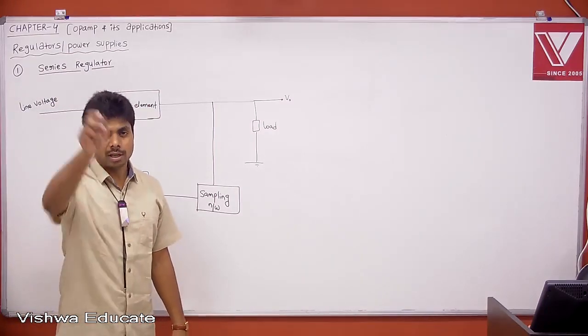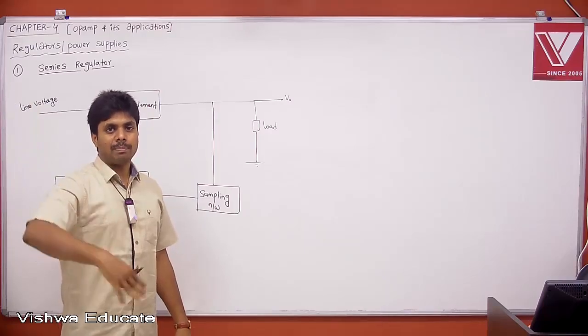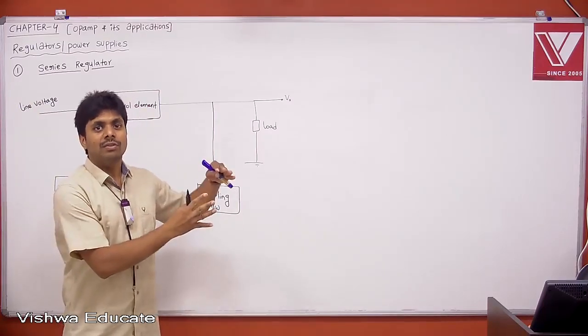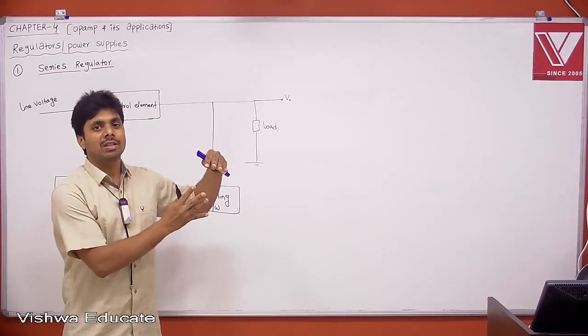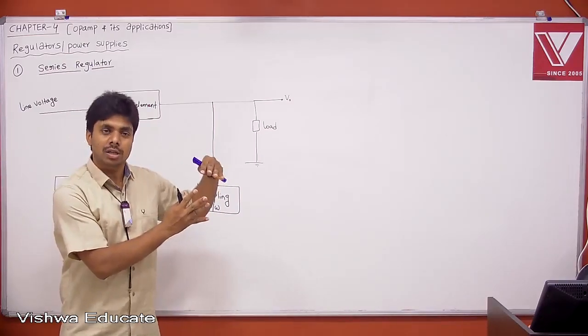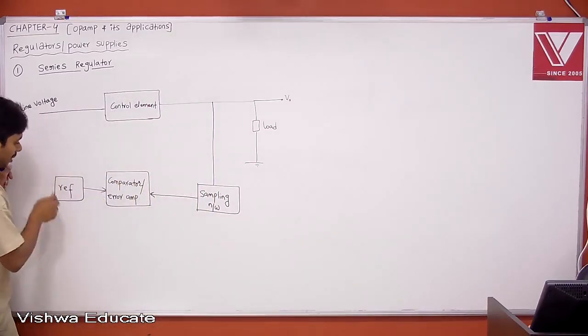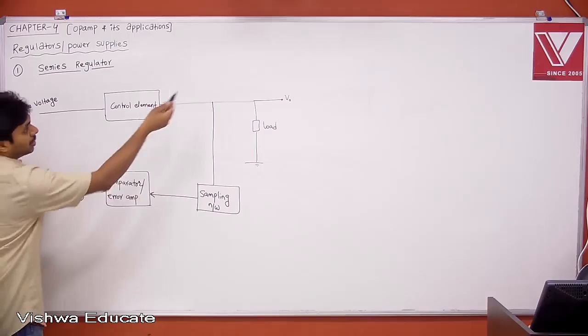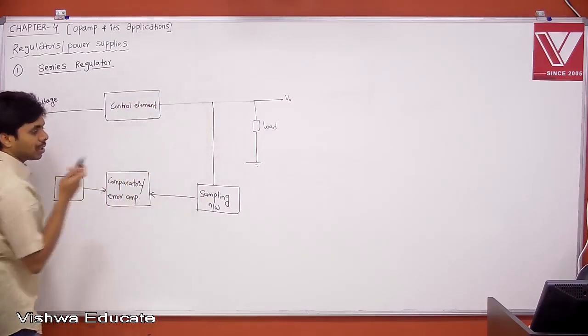The PLL also has feedback, right? Your output frequency is sampled and then fed back using a divider to the phase detector with respect to the reference clock that comes from the crystal oscillator, because we assume that the crystal oscillator output clock frequency is constant and stable. This is your reference voltage. The stability of the reference voltage is the stability of your output voltage. If this is absolutely constant, your output also will be absolutely constant.